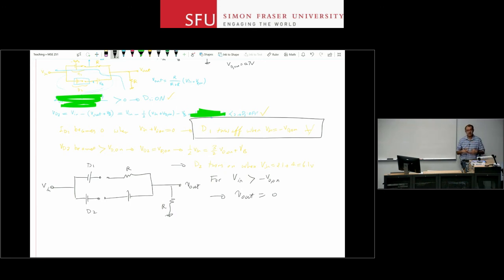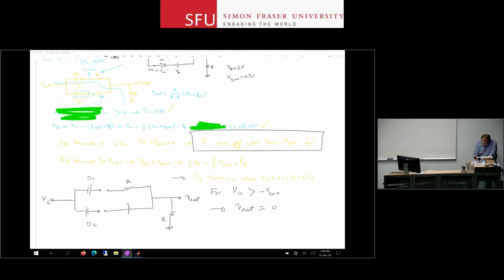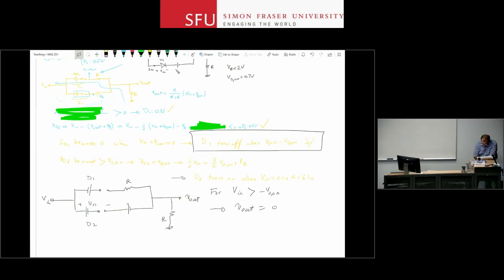I think the next change that will happen here will be because of D2 switching its operating region. Remember, D2 is from here to here, VD2. So this is my D2 pointing this way. This is the direction of the current. For D1, it was the opposite. Right? Once a diode switches state in a linear circuit, as you monotonically increase or decrease the input voltage, they usually do not switch anymore. Right? So as long as you do not have memory elements.